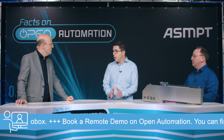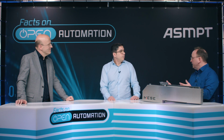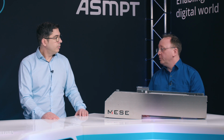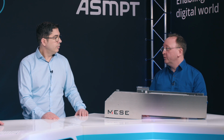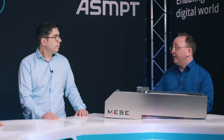And that means now we can distribute components from the CPP head to the CP20 P2 head, but we have also enhanced the capabilities of the CPP head. Right, Wolfgang? Yes, Jetula. We did enhance the capabilities, as you said. The maximum placement force has increased from 10 to 15 Newton, the maximum component weight from 8 to 20 gram, and also the maximum height of the component has increased from 11.5 to 15.5 millimeter. But that is not all.